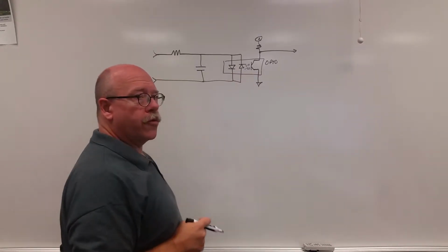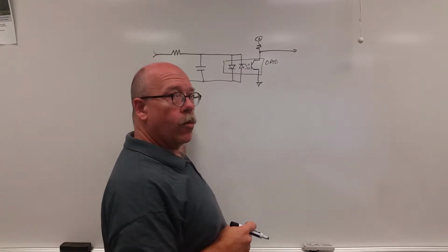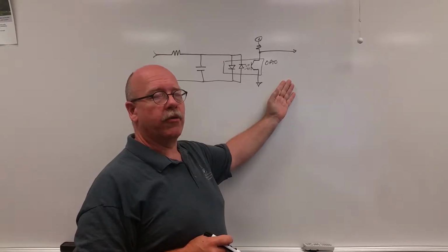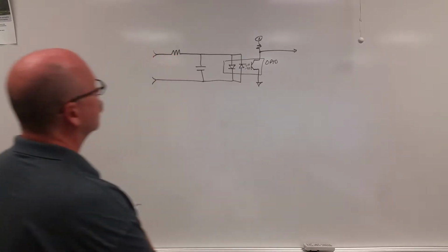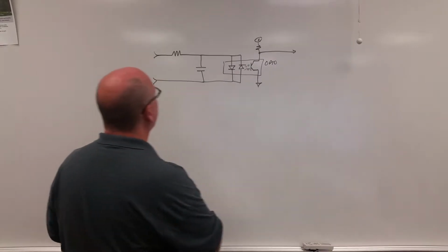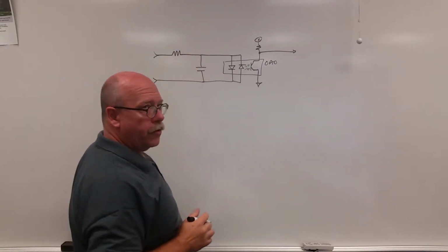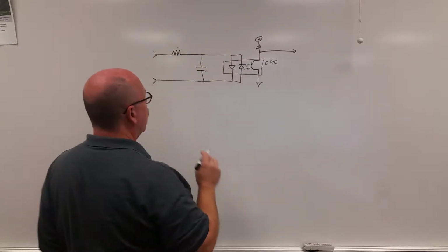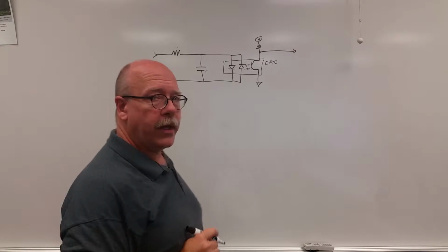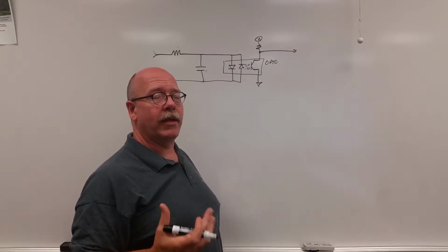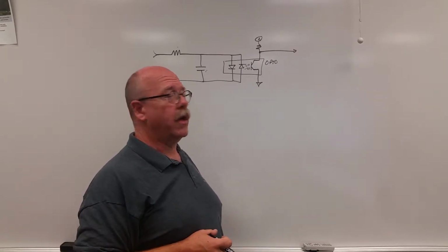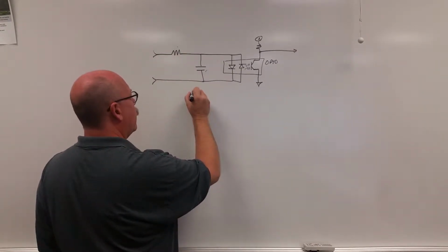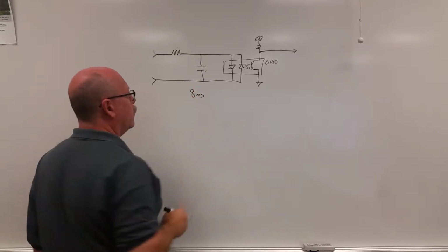The optocoupler is used for isolation from the real-world devices to the bus contained inside of the PLC microprocessor. Due to the way the input is configured with a resistor and a capacitor, it will limit the speed of a signal that can be detected by the device. According to Allen Bradley specifications, the minimum rise time is approximately 8 milliseconds.